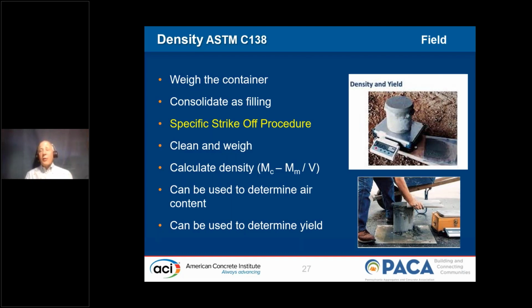The only way to solve that argument is to do a unit weight test. Then you go over to the mixer driver and say, give me your printout, show me how many pounds are in that truck. And real easy, within a few seconds, we can determine how many yards of concrete are in that job. So we know who's right, who wins that argument. Unfortunately, in our business, I think there are many people who enjoy the argument more than they enjoy the answer.